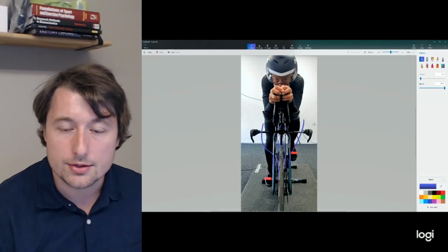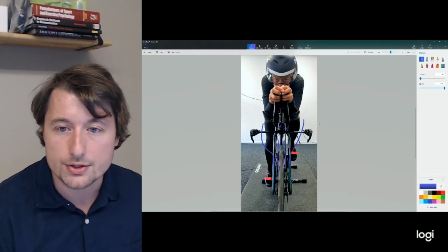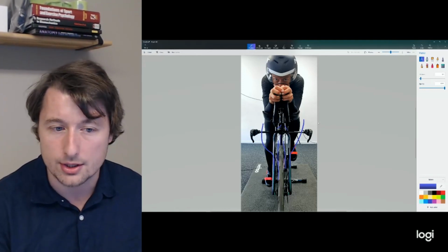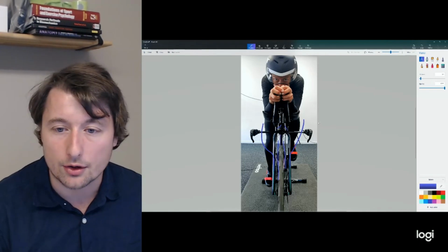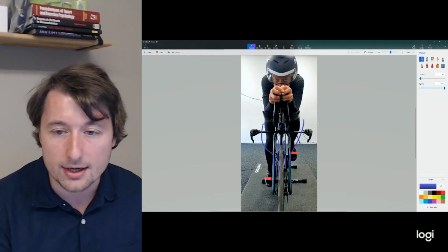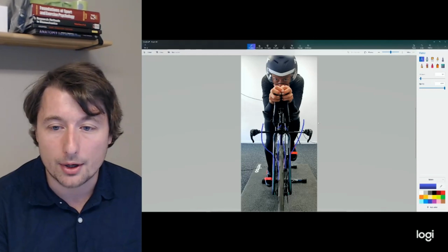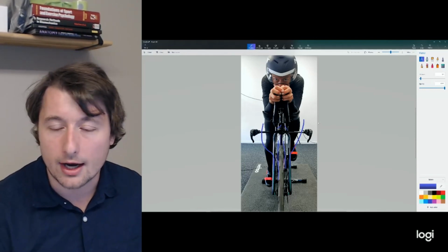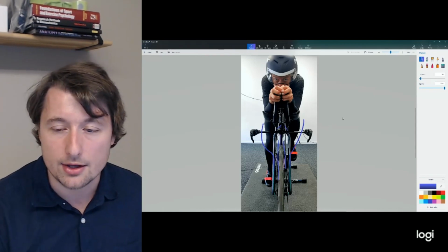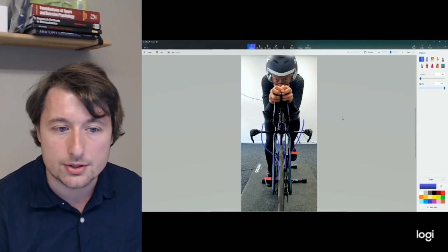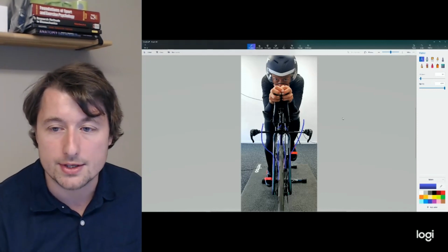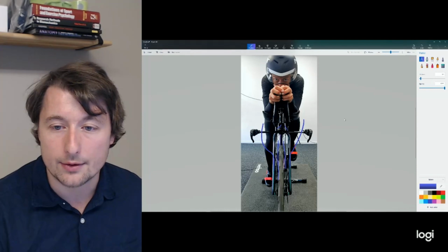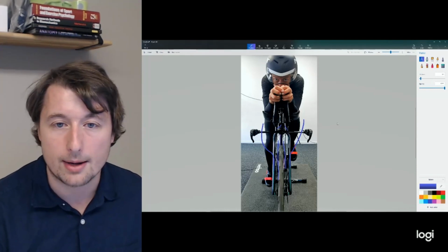So what we're going to be working on with this course is a lot of the things around how you can improve the body positioning aspects of you. We'll discuss components, bikes, and helmets later on as well. But a lot of what we want to do is improve your awareness of how you're sitting on your bike yourself, and how we can optimize that to get you to move through the air better by reducing both the CD and the A part of the CDA, and in turn getting a lower drag force by allowing you to move through the air better in a smaller shape.